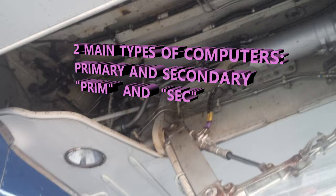And the abbreviations that you're going to see in manuals are PRIM for the primary computer and SEC for the secondary computer. I hope that gives you a brushstroke on the functions of each of those and the difference. The secondary computer, in particular, is interfacing or having to do with the pedal trim control, where the primary flight control computers are not.